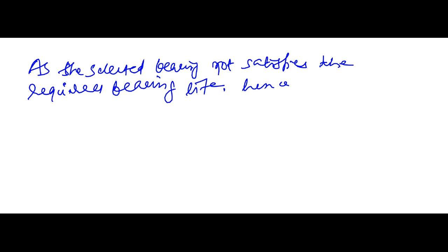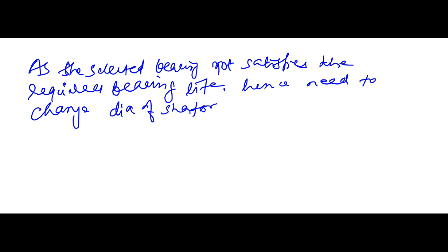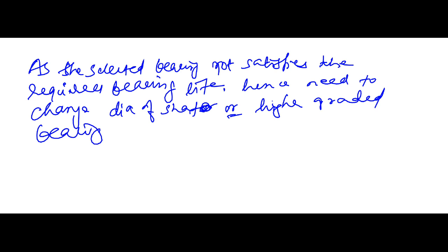Hence need to change the diameter of the shaft or choose a higher graded bearing. That is, L calculated is less than L required.